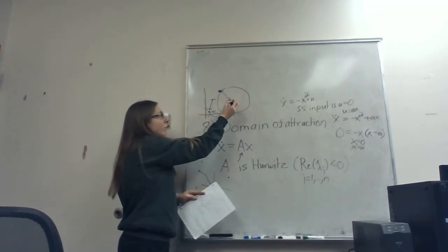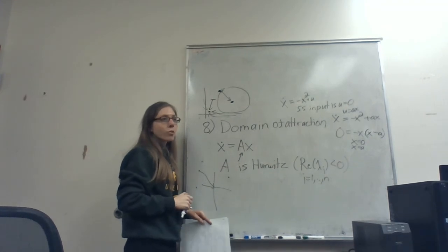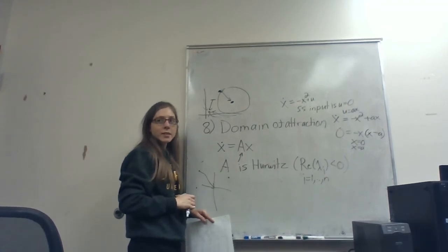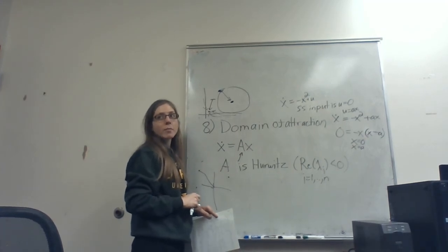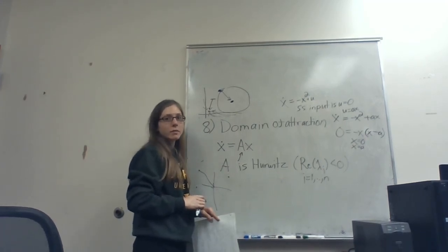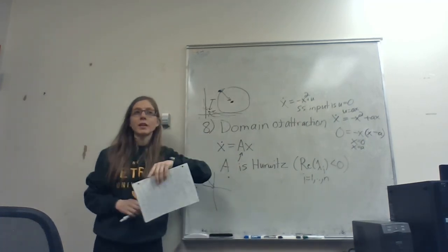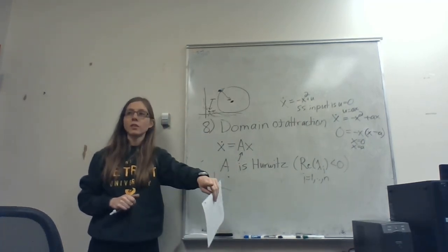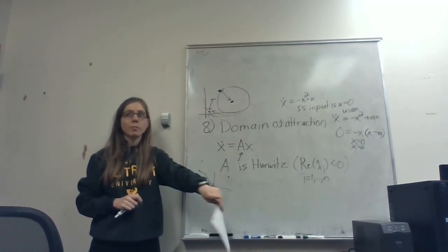So if I have multiple steady states, I might be able to find a controller so that now I only have one steady state under that control law. Then I could try to make that globally stable. I could try to make a globally stable steady state using my control law and all those different things. So I can make unstable steady states become stable because I literally changed the dynamics. And if I have a different dynamic model, now I can make different steady states stable or unstable.